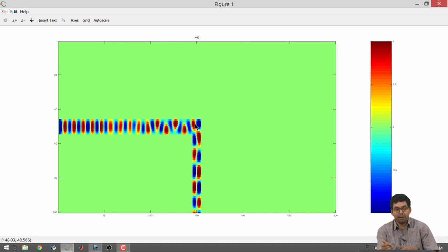So, it means that in order for me to do a real experiment, okay, I need to have a source. The source should be of the size of the waveguide, all right, in order to excite some clean waves inside of the waveguide. And in order for me to detect that I am having waveguiding action, I could keep a detector on the other side.